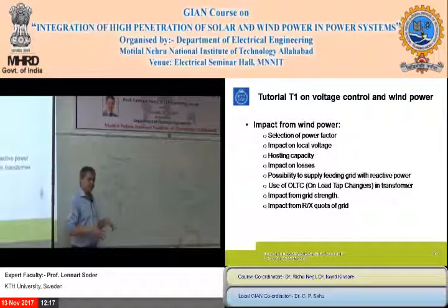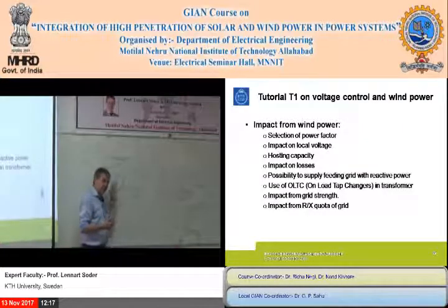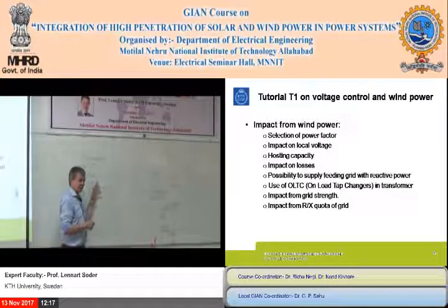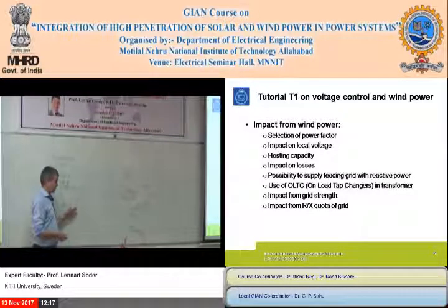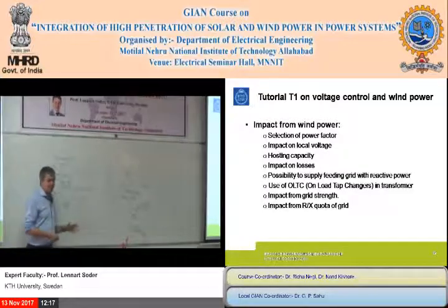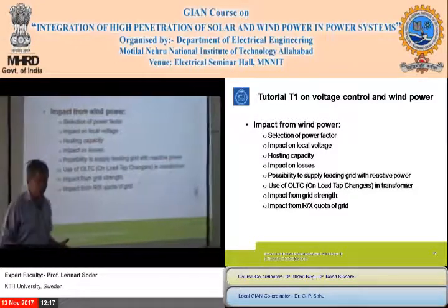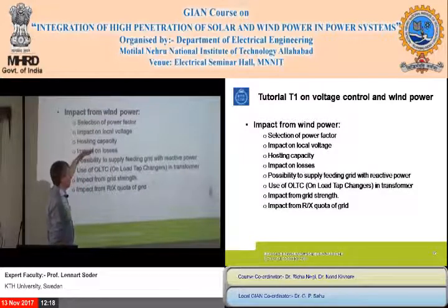But you can also have extreme systems where you have dominating resistances, if you have cable networks, because cable networks have very low reactance. This means that you get nearly only resistance. Then, if you produce more, you don't get so much voltage drop, but in some extreme cases you can get more losses. We have seen cases like that, but it is not the way you normally operate. Of course, it is extremely important not to produce more power only to create losses. That is no value.